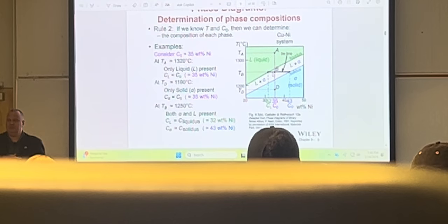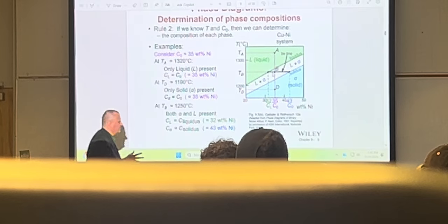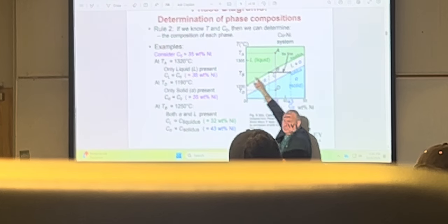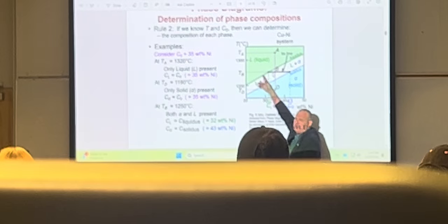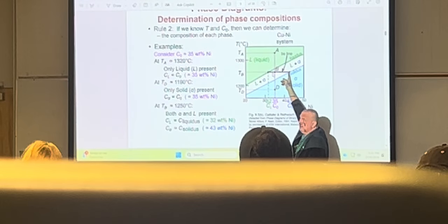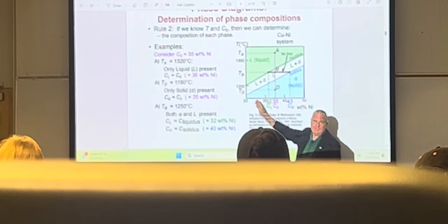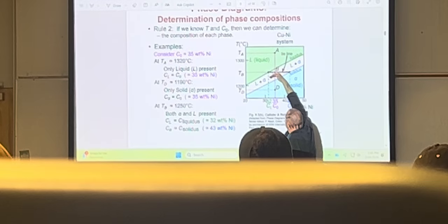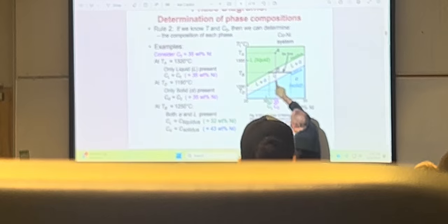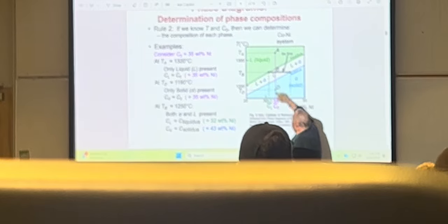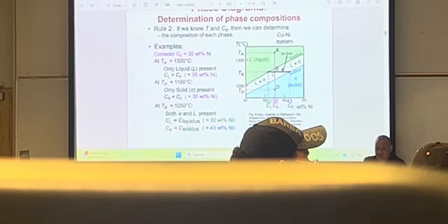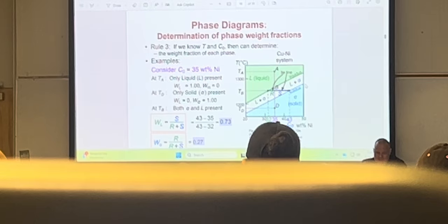And we calculated the equilibrium size of those nuclei, about 10 nanometers or so. And at the expense of the liquid, the atoms of nickel go towards the solid phase. That's why there's less nickel than 35%. And it's dynamically going down, boom, boom, boom, until we hit this point, where we start with 35, we end up with 35. If you get it now, it is awesome.